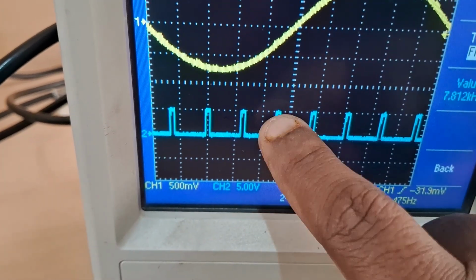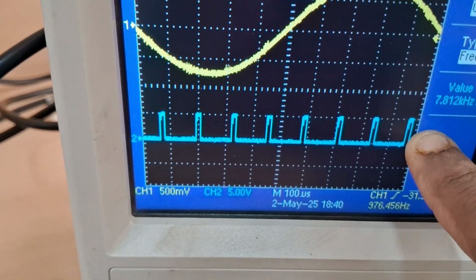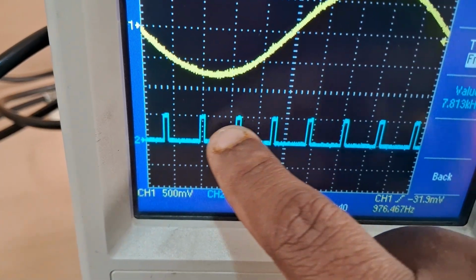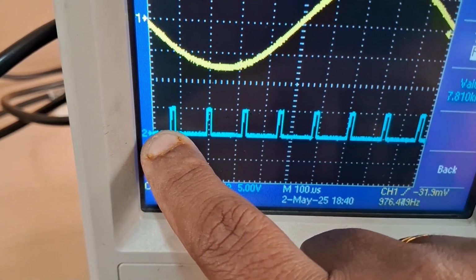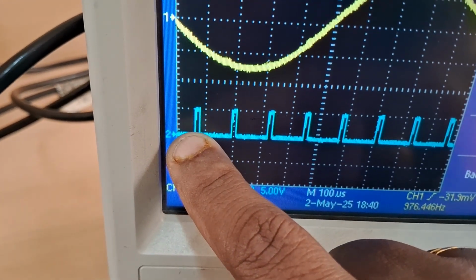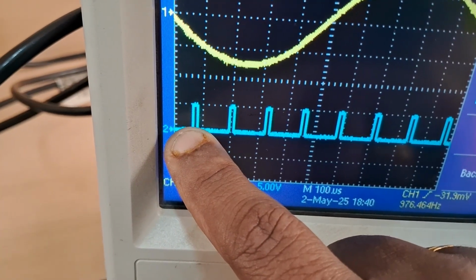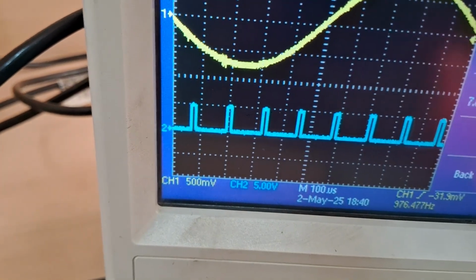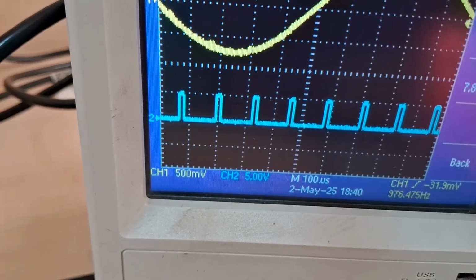So there are going to be 4 sampling instants in the positive half, and 4 sampling instants in the negative half, right? Now I'll remove the analog signal, and we'll see the synchronized waveforms for SC and EOC. What is EOC? EOC is end of conversion.